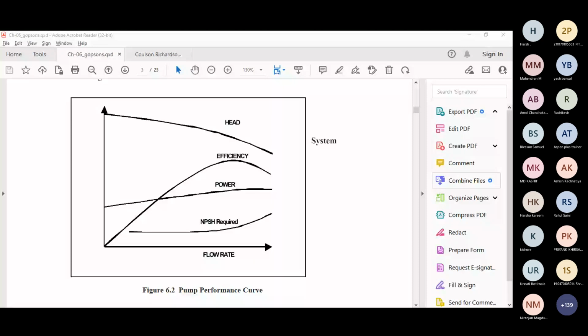Correct? If I am getting it right, you are saying that if I pump water about 10 meter, then 1 kg pressure will be shown by the pump discharge gauge, and the same pressure will be shown when I am using mercury, but it will be lifted up to 760 mm Hg. Am I right? Yes, correct. So it will again show 1 kg pressure, but it will be lifted up to 760 mm of mercury only. It will not be able to discharge that mercury at higher heights. Is it clear? Yeah, I'm getting it.